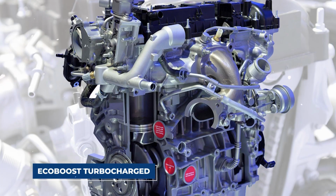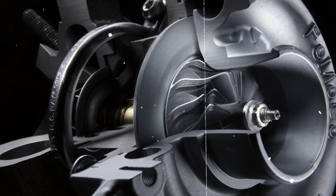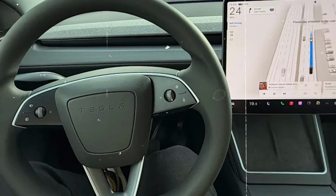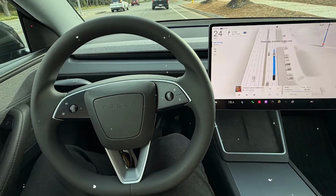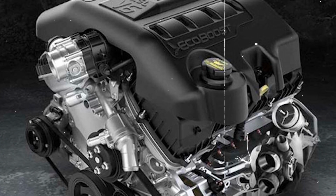On EcoBoost turbocharged engines, the adaptive learning also affects wastegate control. The computer starts opening the wastegate earlier to limit boost pressure, thinking you prefer fuel economy over performance because that's how you've been driving. This kills the aggressive turbo spool that makes EcoBoost engines exciting to drive.